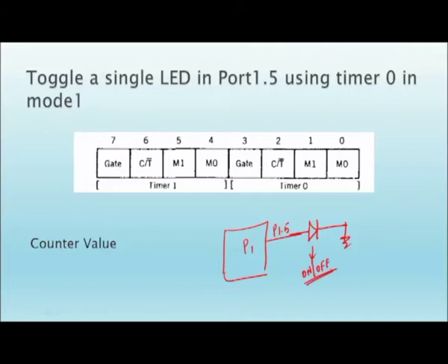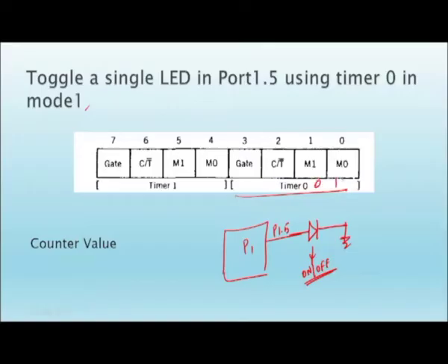Okay. Then I am using timer 0. So, for timer 0 only 4 bits I have to use, right. Here no need for the others, and I have specified mode 1 also. For mode 1 you have to assign the value 0 1. Now, as a timer, you give the value 0, and the gate also should be 0.